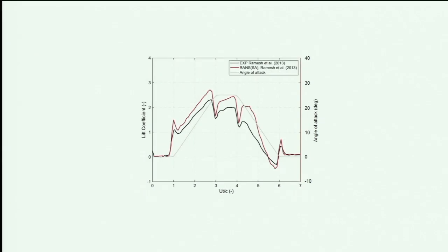When we check the results from the literature, you have one experiment data and one numerical data. Here you can see the differences are large, especially for the lift coefficient, here it is almost 0.7. Here he used RANS simulation, and we know RANS has been developed for very high Reynolds number, where the flow is treated as fully turbulent.